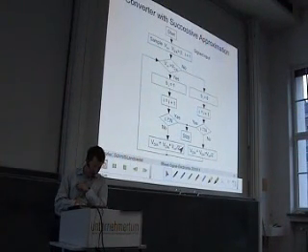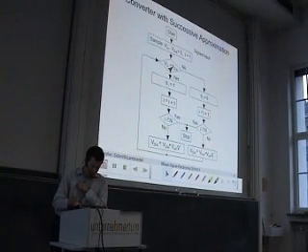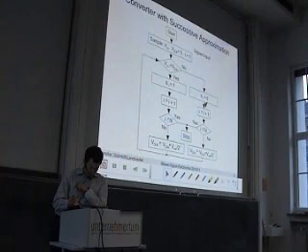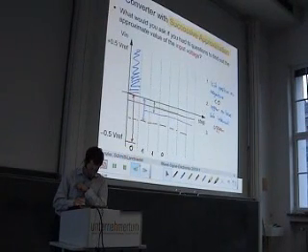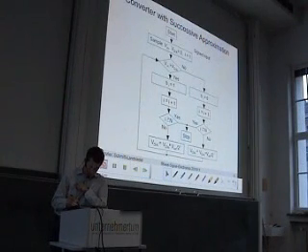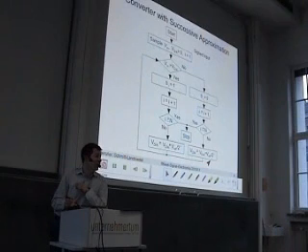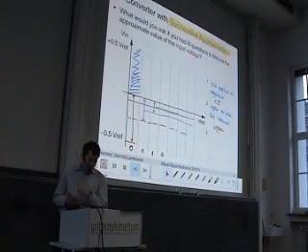Or if the input signal was smaller than the threshold, then we set the respective bit to 0, like we did it here, and we subtract Vref over 2 to the power of I from this internal voltage. So exactly as we did it here.